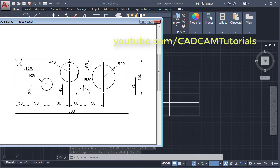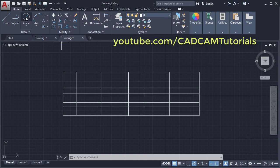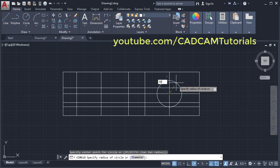Now we will place the circles. Now this is circle of 50 and it is at the location of first line from this side and second line from the top, and radius is 50. Click on circle. So here is the first line and second line from the top. Give the center point, give the radius of 50, enter.